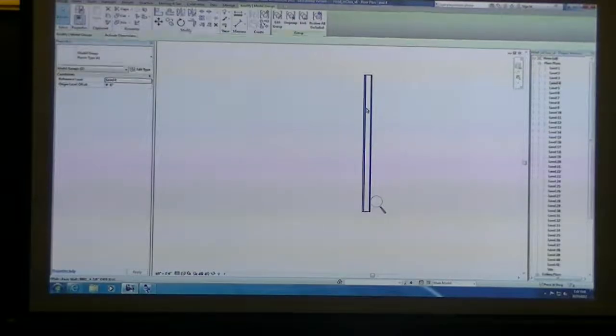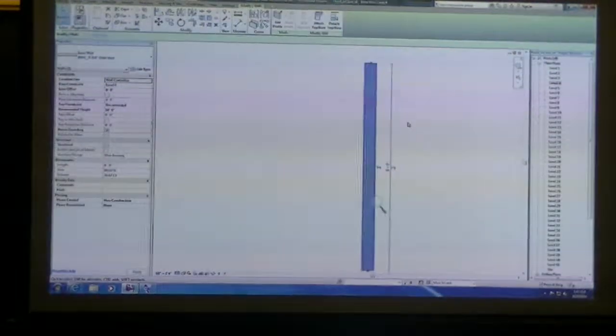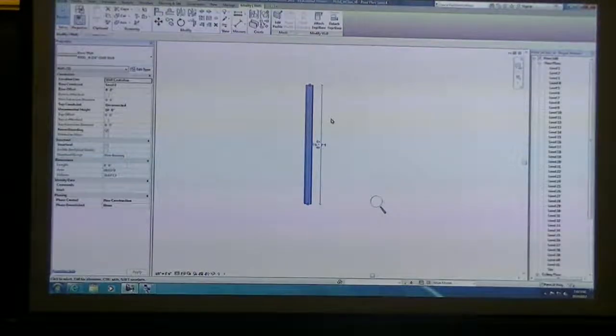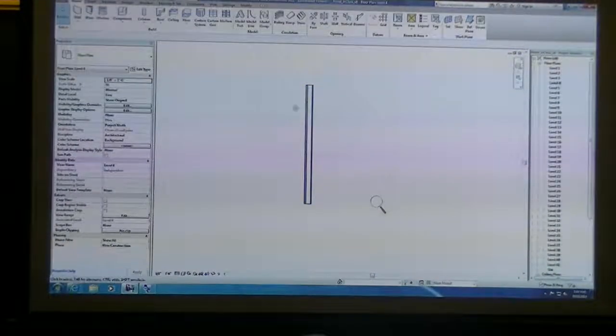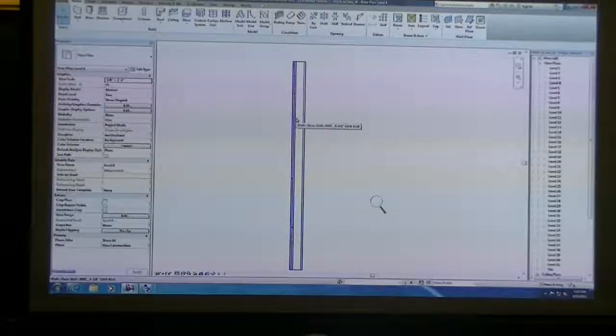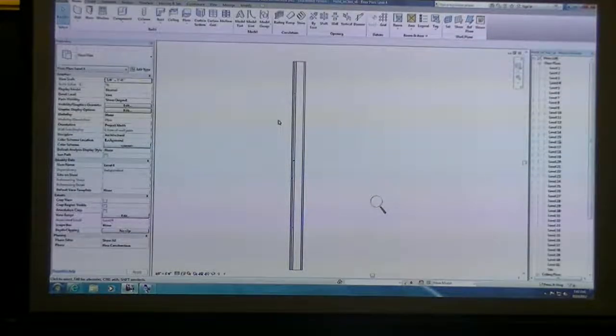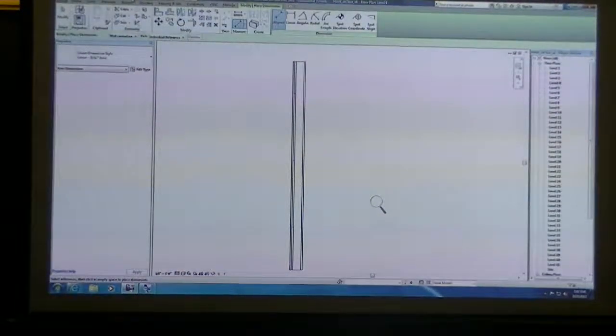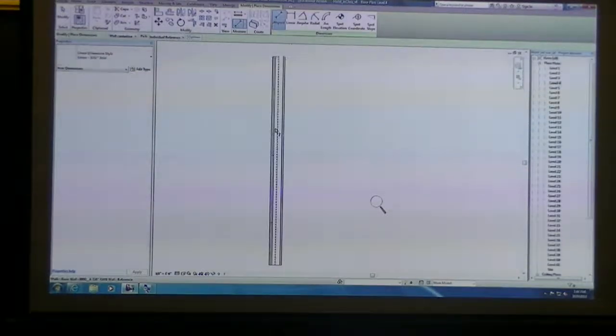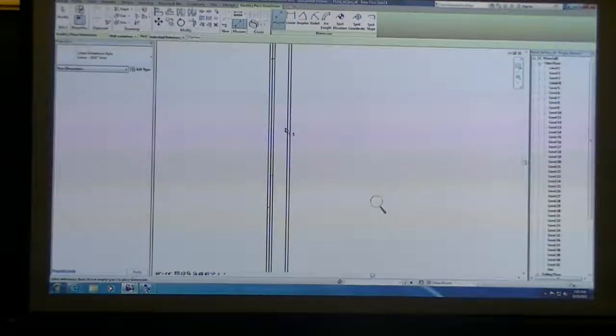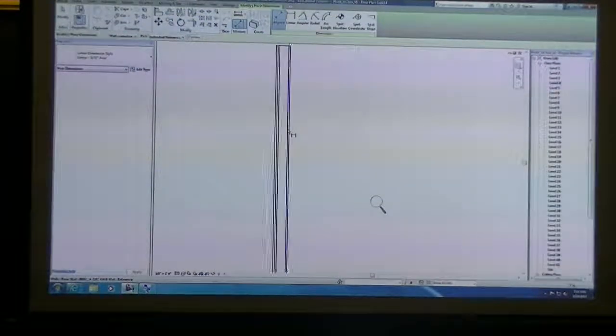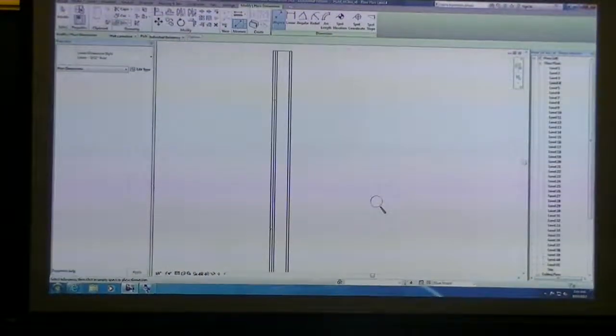We're almost done here. I just want to point out that when you're in construction documents, you want to see all these different layers in your floor plan because you want to be able to identify and look at all of the different layers that I could draw to or snap to with my dimension string. And when you actually start dimensioning walls, you're going to snap to the face of stud and not the face of gypboard, depending on your office standards. And having all those different layers in there gives you that ability to select and tab over so that you can make that dimension work out.